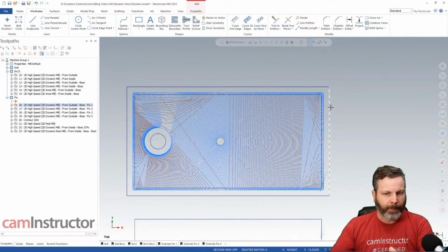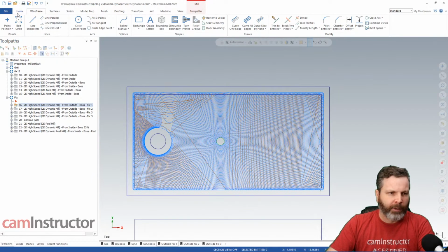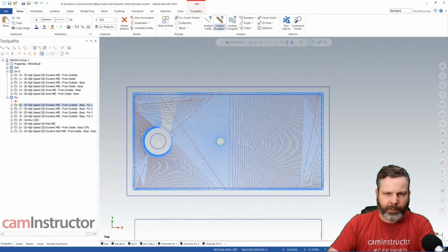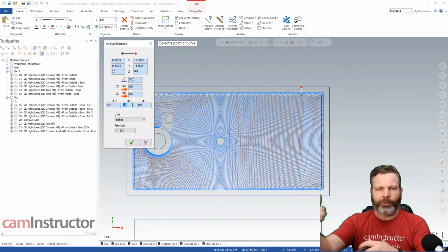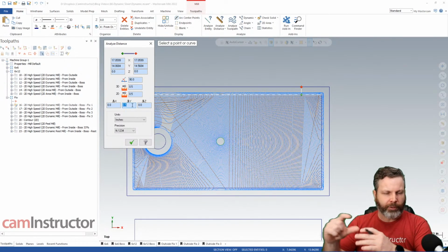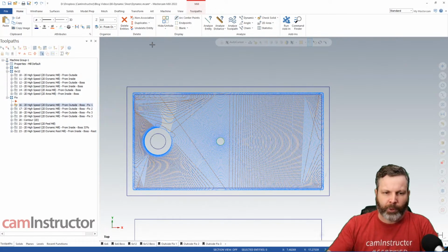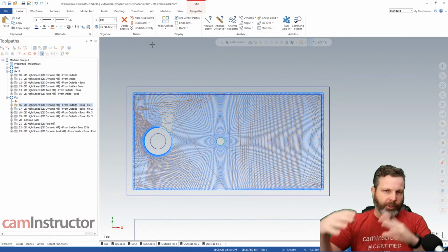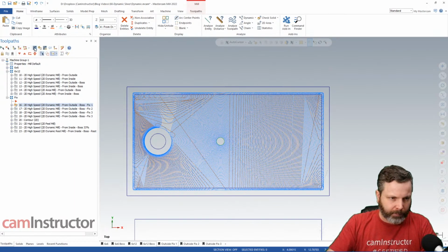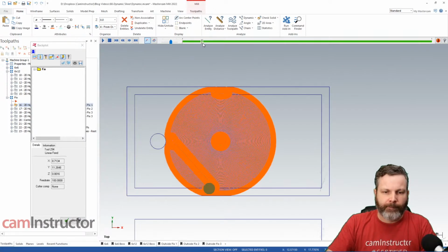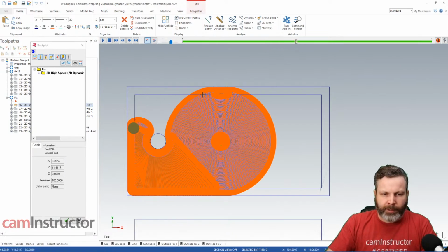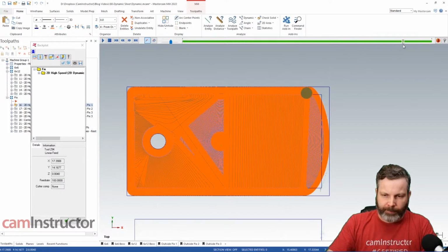want to cut. So I'm using a 3/4 inch cutter here, and I believe I offset the distance here, analyze distance from here to here. That's 1/2 inch in radius, so that's more than the 3/8 radius of the cutter. So I've expanded the shape I want to cut, used that as my cutting boundary, and this will, let me just move this guy over here. This now cuts that entire shape that we wanted. We are avoiding the sliver.